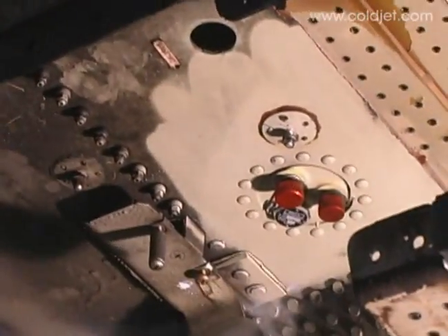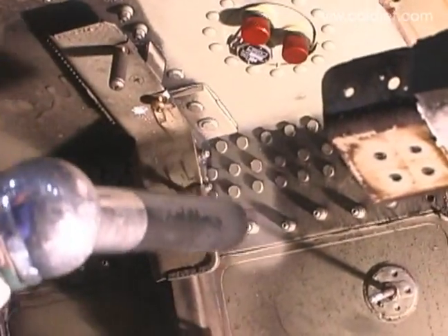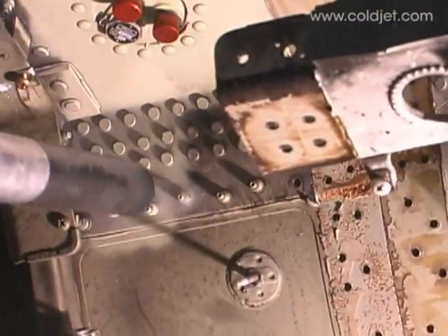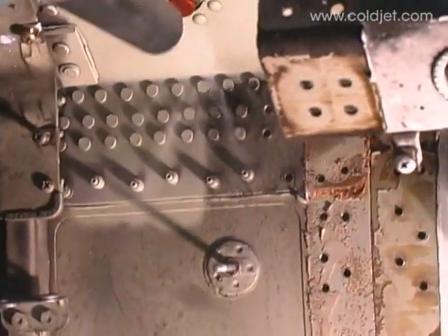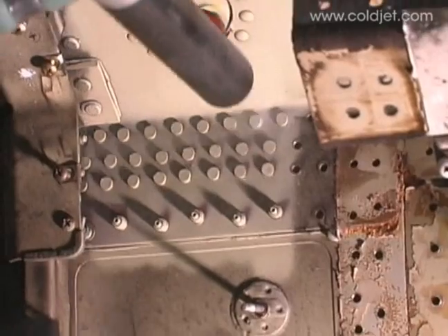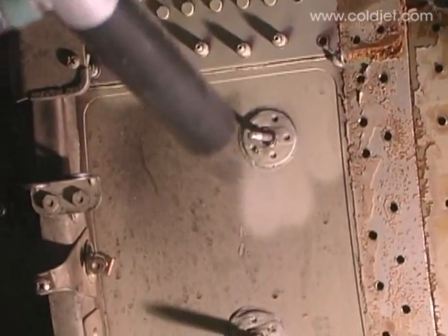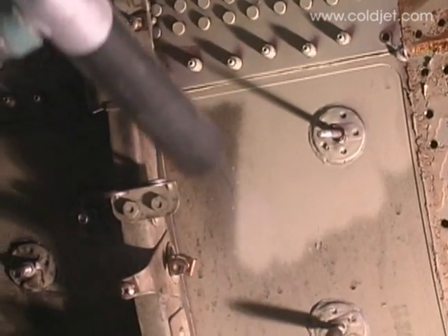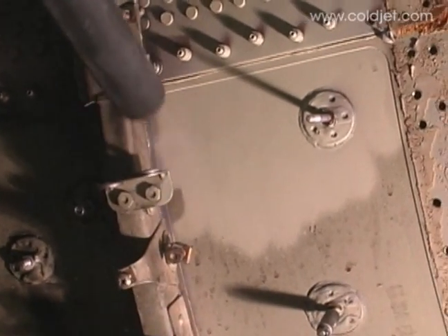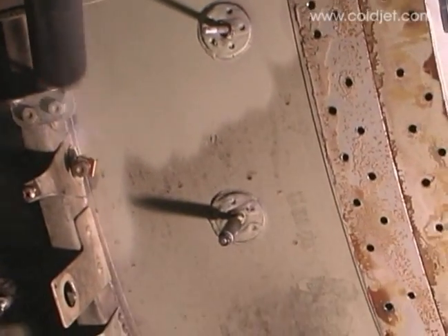And solvents that we use to clean those areas have come under a ban from the EPA. What we found was that the dry ice blasting took care of that need excellently. In other words, we were able to clean better than we could with solvents. And in so doing, we had a higher success rate in promoting that adhesion.